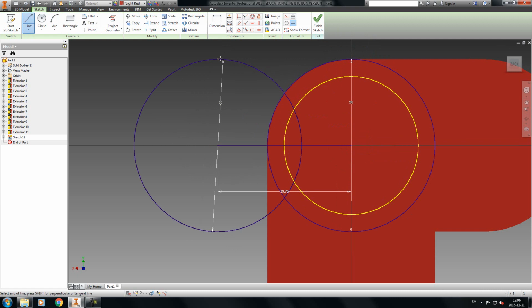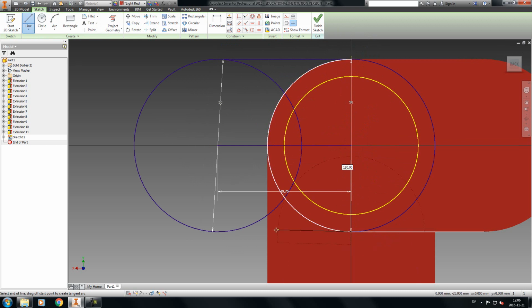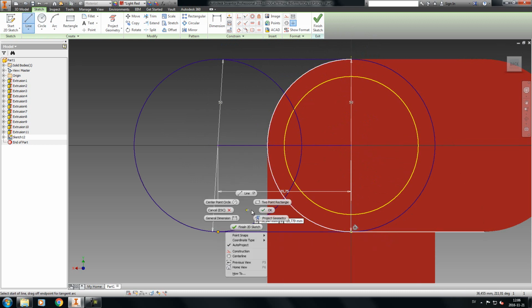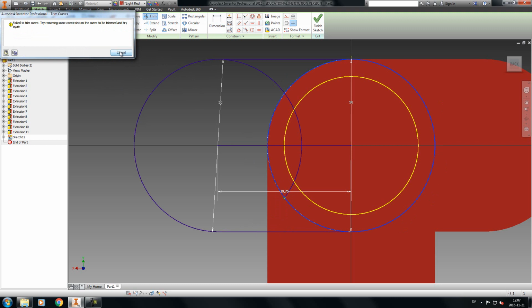Press OK. Choose the line tool. Try to snap it. Draw it between the two edges. And then you choose the trim tool again and try to trim away all the surfaces. Now, you see, this is what happens when we haven't removed our dimensions previously. Because the trim tool has some limitations, namely that it cannot trim things that have dimensions attached to them. So we will have to make sure that we have selected these dimensions, or sizes, so to speak, the white dotted lines with numbers on them that we deleted previously. We have to delete those before using the trim tool.